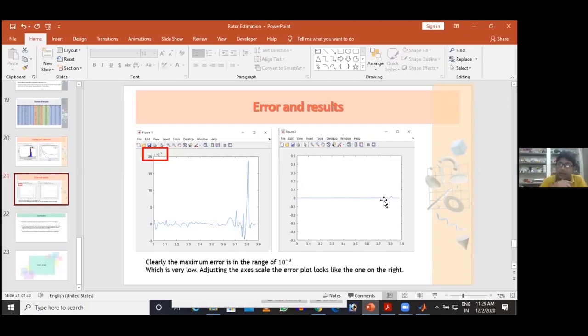So now, instead of a static system, I need to implement an additional machine learning hardware through which it will instantaneously estimate the inverse rotor time constant, and that will be fed wherever the inverse rotor time constant is needed in the vector control. So this is the concept.